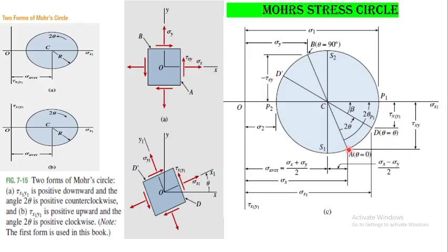Now you will calculate the other point, which is the B point. This is sigma x, sigma y. Now when you go for the B point, again from the origin you move and put sigma y, which has a numerical value less than sigma x. For example, if sigma x is 8,000, then sigma y will be some 5,000. So you move here until you calculate the value, and you put a point over here.